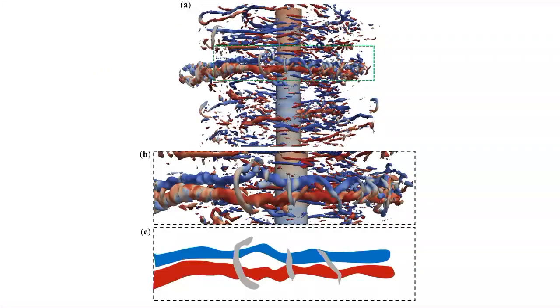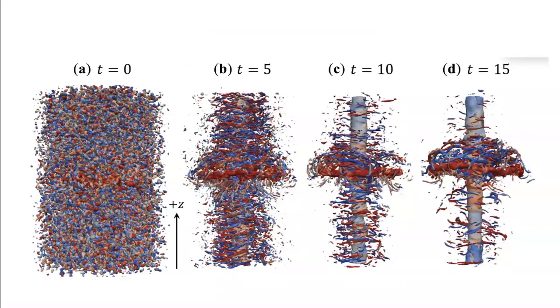And you see, not only is there organization of the small-scale turbulence, there is a hierarchy of alignment of some of the vortical structures. You have a big vortex column, then the ring, and smaller organized structures with axes perpendicular to the axis of the ring, while the ring's axis is also perpendicular to the vortex column. And here's more detail of this